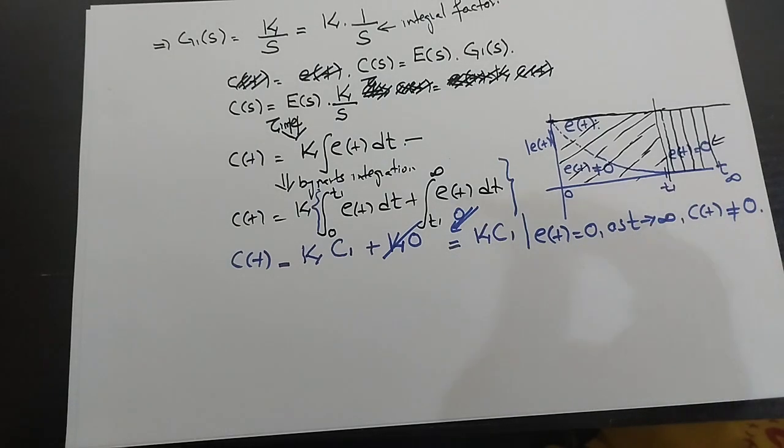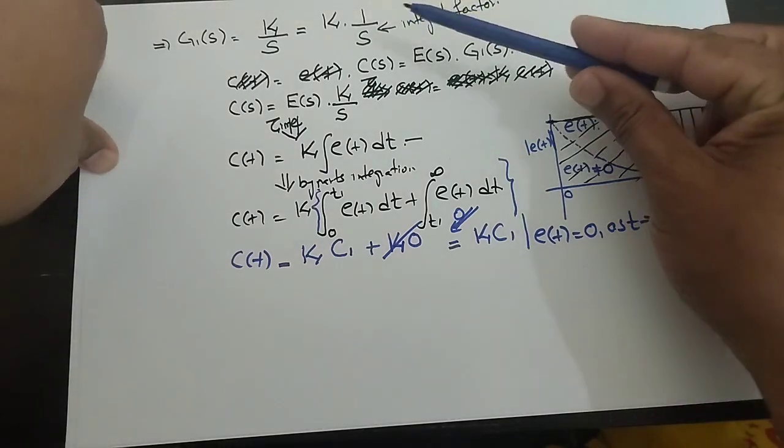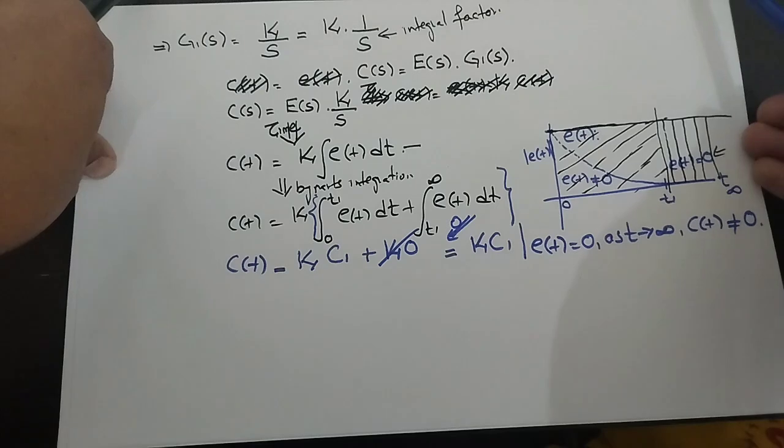We should have some output signal so that we could get our desired response at the output. If our controller makes the error equal to 0, yes, that is the desired point, but if it is also making the system output equal to 0, then this is a useless activity. To cater to this problem, we have incorporated an integral action into the system.